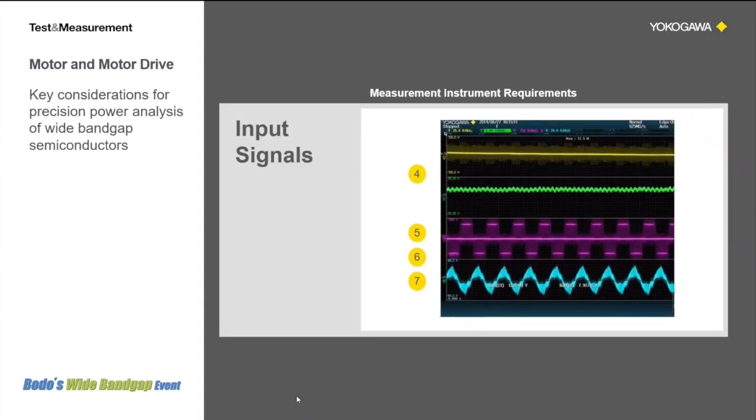First of all, it is important to understand the signals that are generated or influenced by an inverter. The top yellow and green waveforms are the DC link voltage and current. As can be seen, both show reflection caused by the switching in the inverter. The purple and blue waveforms are the voltage and current waveforms from one phase of the output of the inverter, where the purple waveform is pulse width modulated voltage, which is used to control the torque of the motor. The next slides will explain where to pay attention to when measuring these signals.